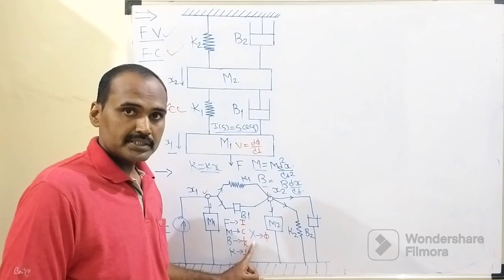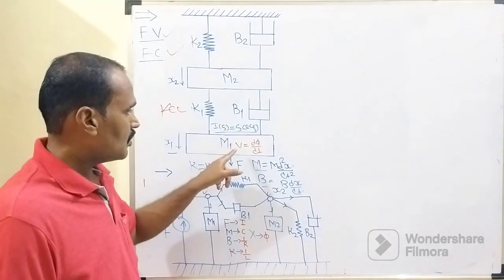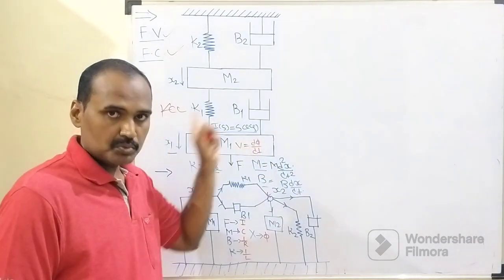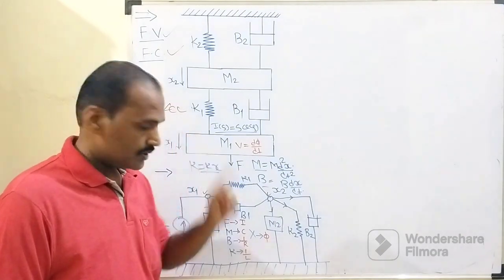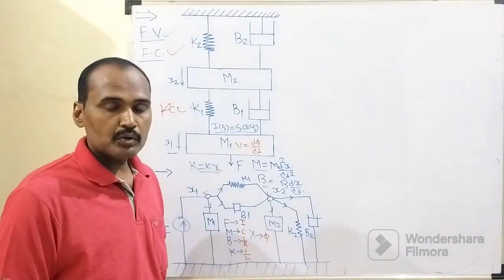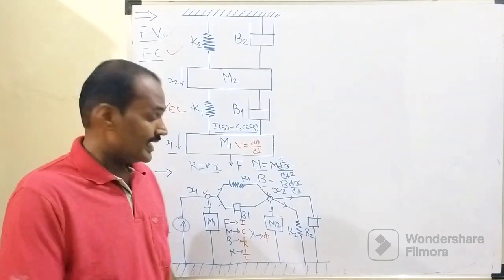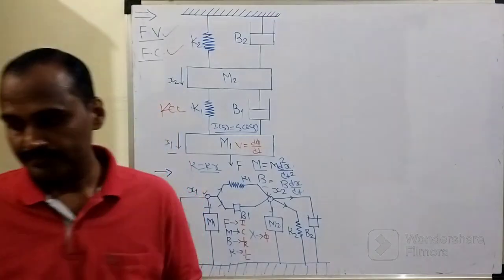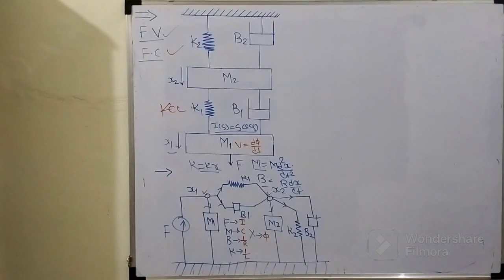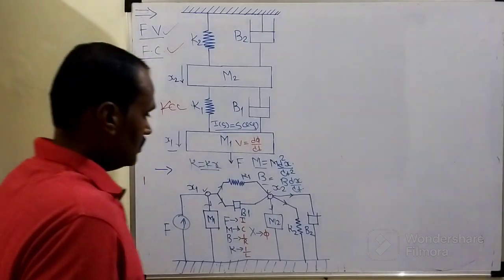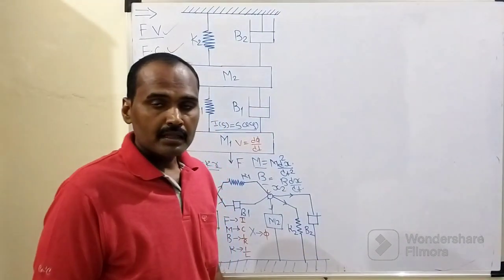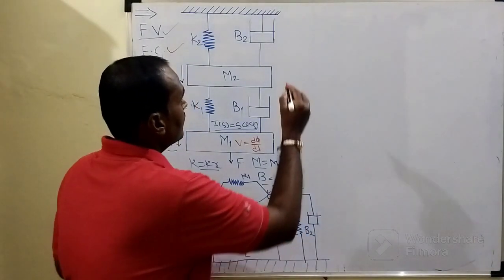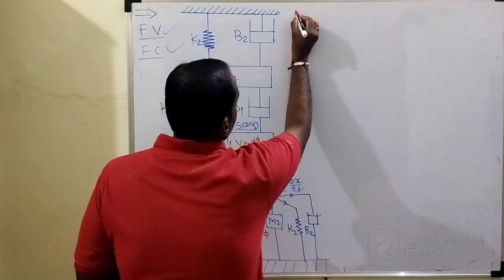Similar to the force voltage analogy, here according to Faraday's law, V equals the rate of change of flux per unit time through that electrical element. So accordingly x is analogous to phi. Taking this fact into account, one more time we need to write the system equation. After applying Kirchhoff's current law, the system equation at node number 1 will be: F equals